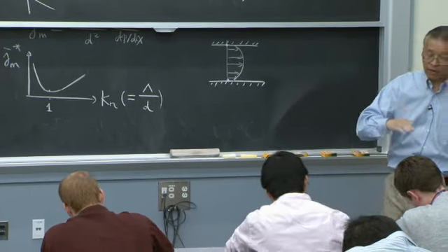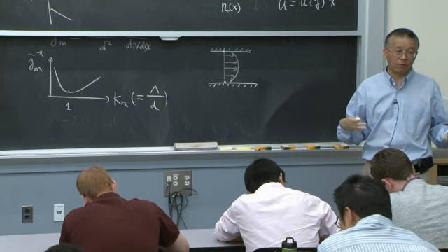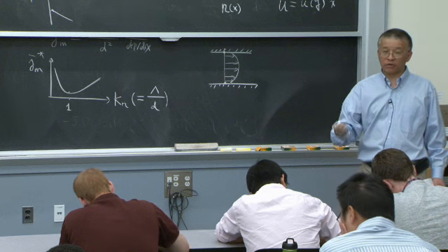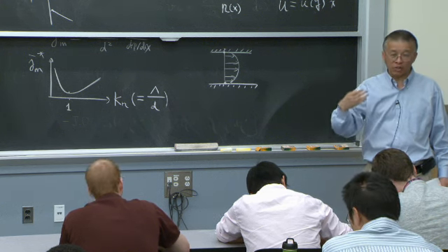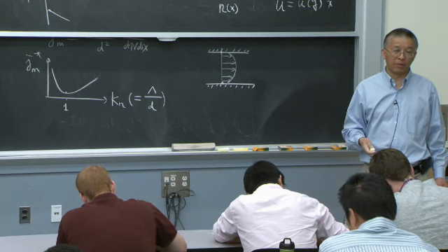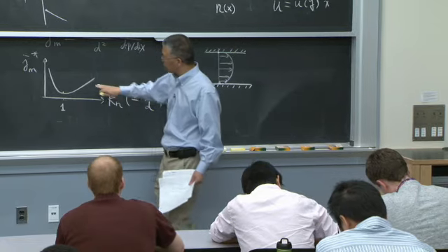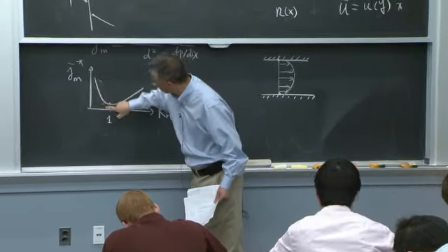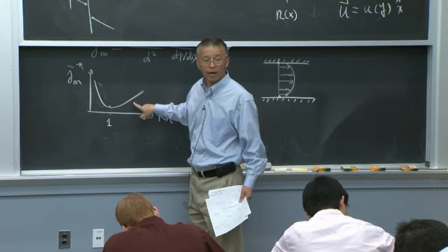Okay, so this is the velocity slip, and in the next lecture we'll discuss it. People have tried various approaches. If you do rarefied fluid or fluid mechanics and microfluidics, you add artificial velocity slip, and in fact you add first-order and second-order velocity slip to try to accommodate this. It turns out that the first-order velocity slip can typically only go to this regime. It cannot go to, say, Knudsen number equals 1 or even higher.